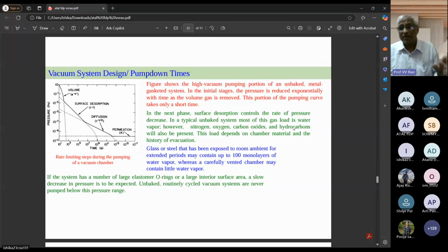That load you cannot avoid because from the walls outside, like 10 days before, it has entered the stainless steel, and now it is coming out of the inner side of it. That will be continuously fluctuating behavior. That's called permeation.